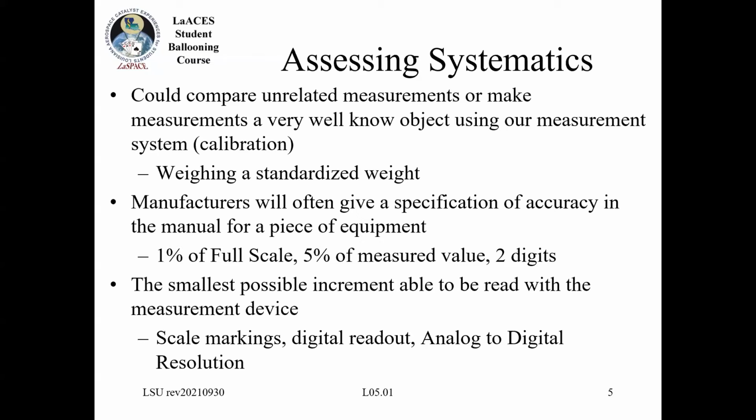If I'm using an analog sensor, which I'm going to hook up to an analog to digital converter, which is something we'll do later in the semester, those digital values will come in fixed steps, right? Because you're reading a continuous analog voltage signal with a digital device.